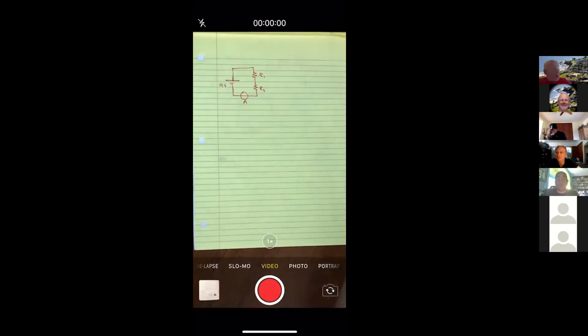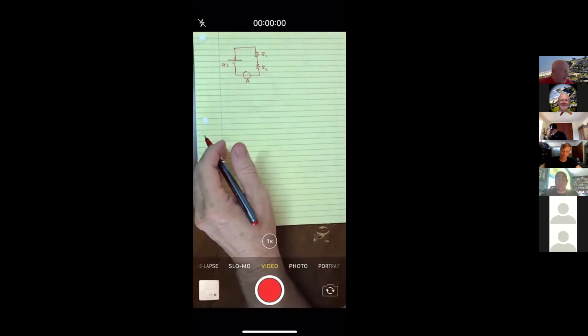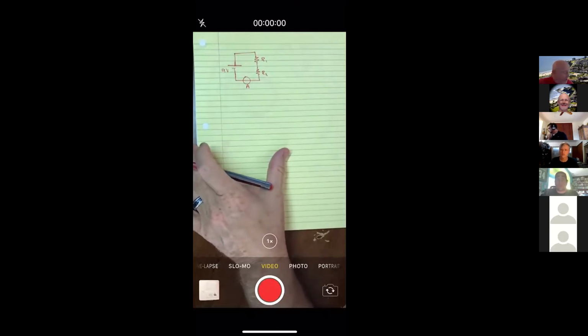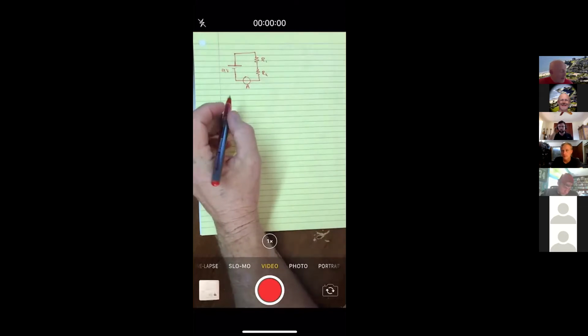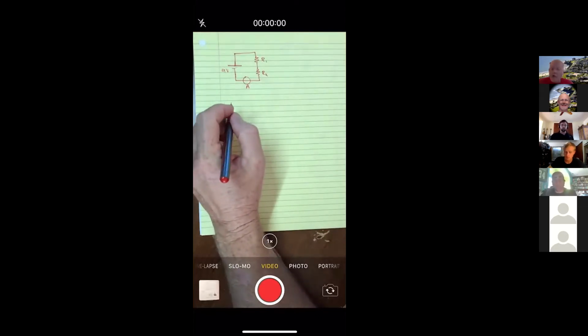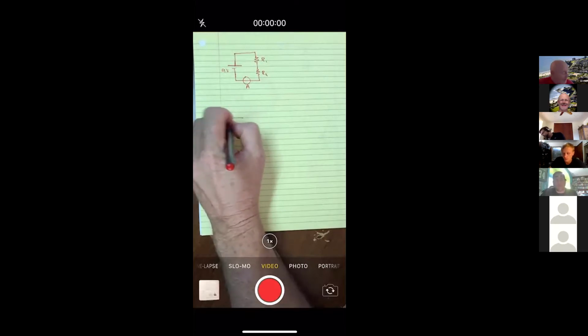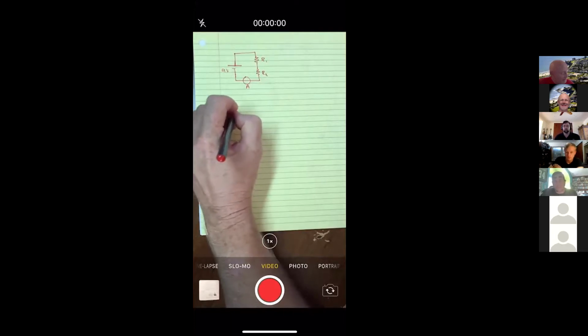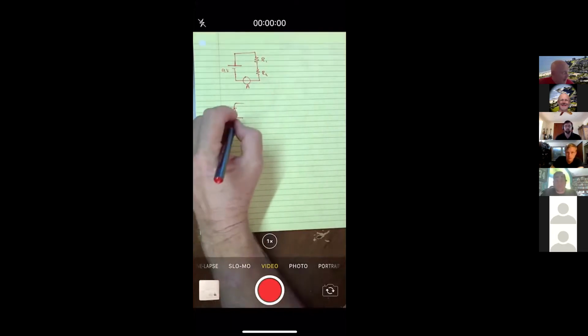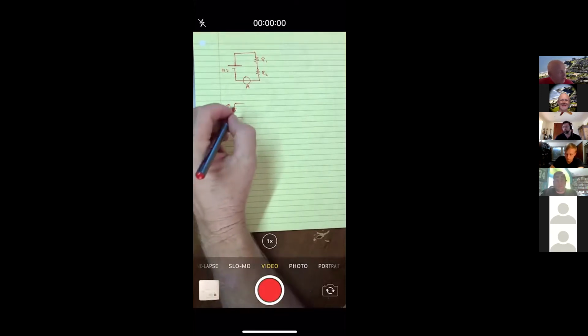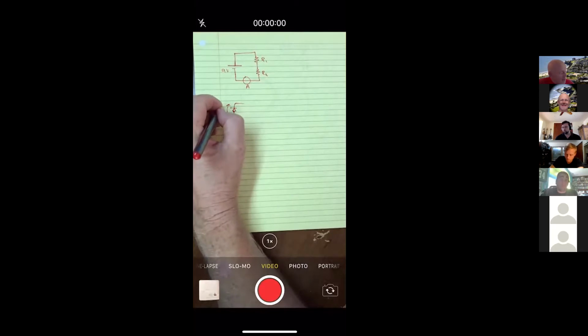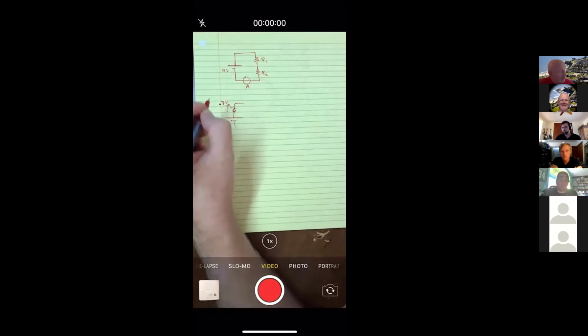Anyways, what I was going to say on top of this, Hunter, is I did a lot of this when I was trying to learn circuits myself, because I didn't have a variable power supply. And so I went and I bought these things called diodes. And a diode is kind of, we like to describe it as a valve. And it just lets the current flow through. But to turn it on, it takes away about 0.7 volts.